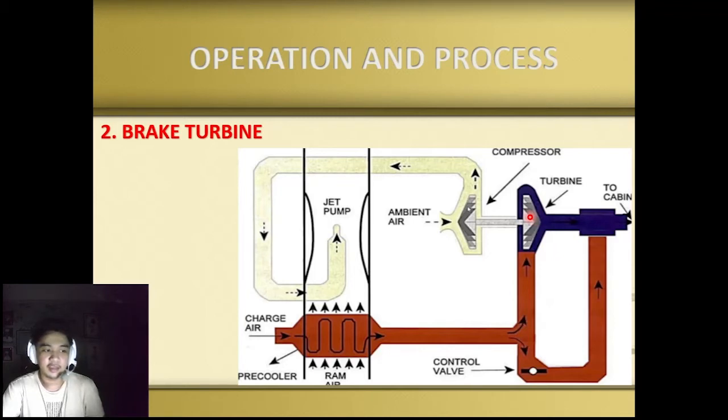And it provides energy conversion which removes the heat from the charged air. In other installations, the output from the compressor is fed into the ducting downstream of the heat exchanger to increase the thermal efficiency of the heat exchanger by jet pump action. This system is lighter because it has only one heat exchanger and the mass flow or weight ratio is better. But unless the jet pump is used, it cannot be used to cool the charged air when the aircraft is on the ground.